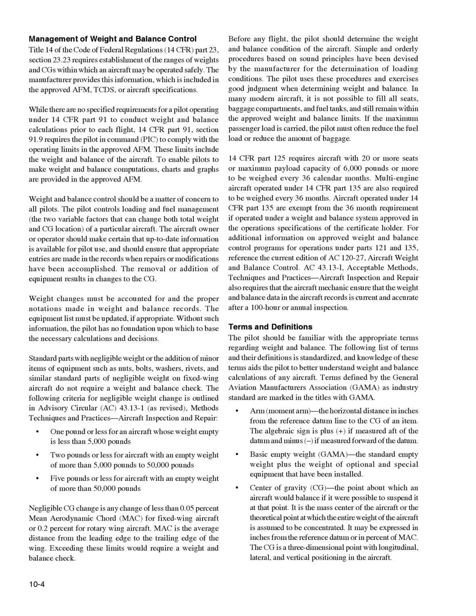Multi-engine aircraft operated under 14 CFR Part 135 are also required to be weighed every 36 months. Aircraft operated under 14 CFR Part 135 are exempt from the 36-month requirement if operated under a weight and balance system approved in the operation specifications of the certificate holder.